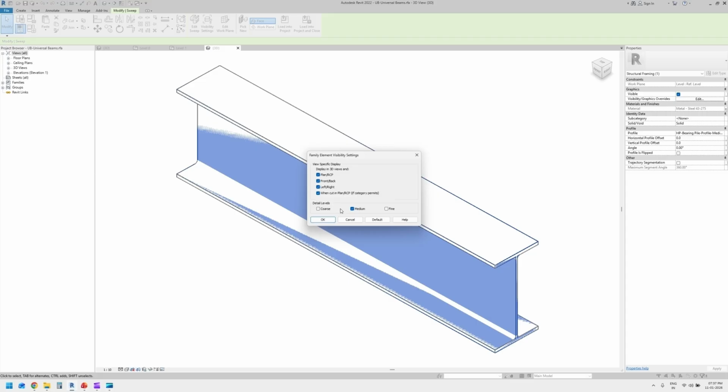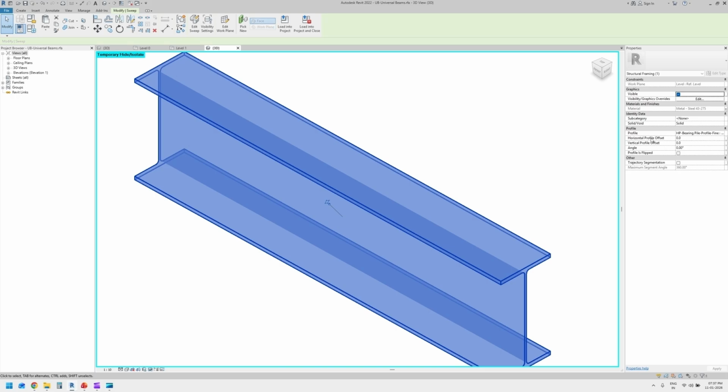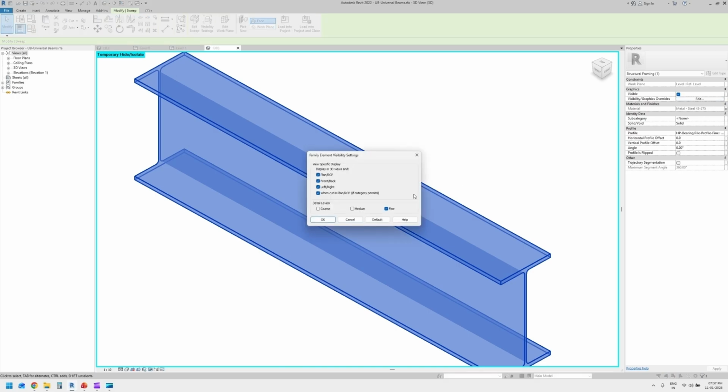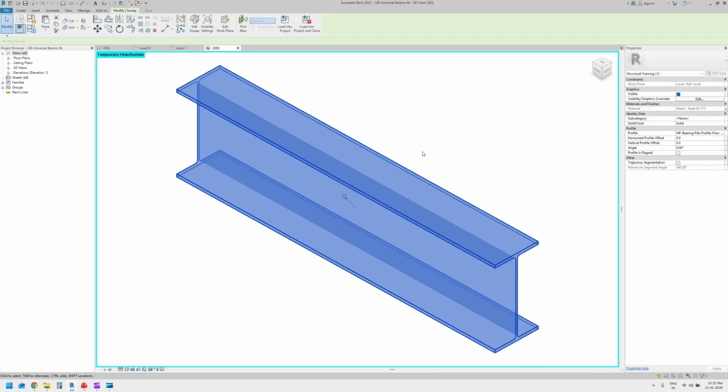In Beam, generally the Beam's 3D model does not appear in coarse, and it has two profiles. One appears in medium and the other one appears in fine visibility. So, if your element is not appearing and you have checked with all the possibilities within the model, try checking that in the family also.